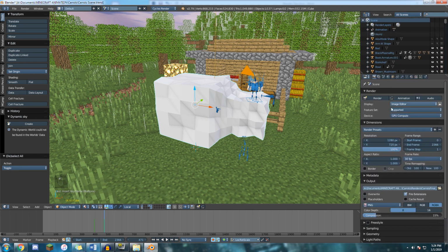You can also type out values in any of these kind of value inputs. Let's say I want to change the end frame to be 30 frames longer. You can simply type out +30, and now we've extended it by 30 extra frames. You can do a bunch of things, like multiply and divide. This is kind of helpful in things like resolution. If you want to just double your resolution, you could just do ×2, or obviously you could have used 200% in this case, but you can multiply, divide, add, subtract, all that stuff.